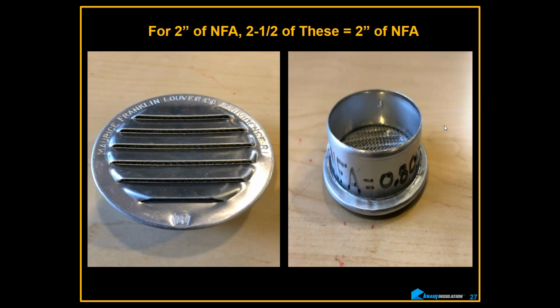Yeah, in hot, humid climates, it's always best to have your vapor retarder facing out. In other words, you're warmer and more humid most of the year, and you also have cold air on the inside because you're using air conditioning. So remember, everything goes from more to less. Hot goes to cold, wet goes to dry. If you have warm, moist air, it doesn't even have to have a wind. The pressure difference, just because of the difference in temperature, is going to be higher on the exterior side of the wall than on the interior side. So vapor retarders want to face the outboard side in hot, humid climates.